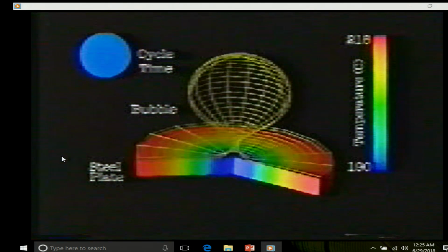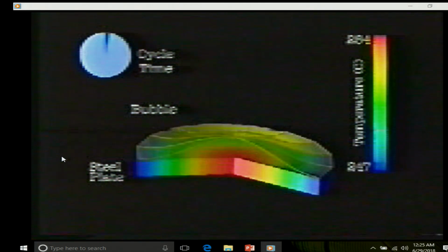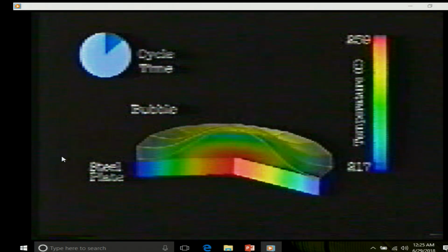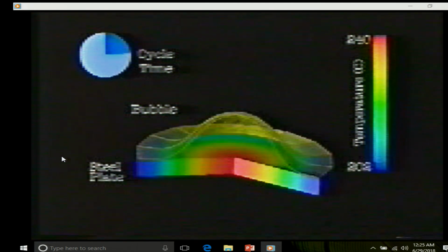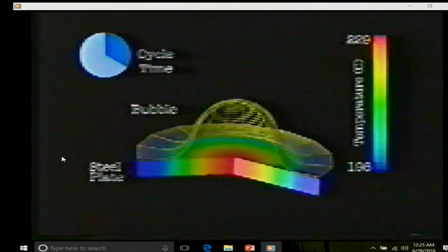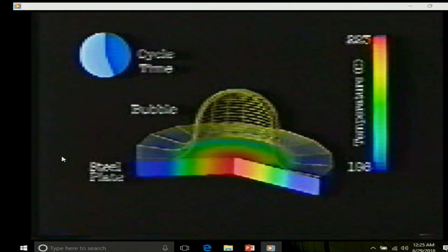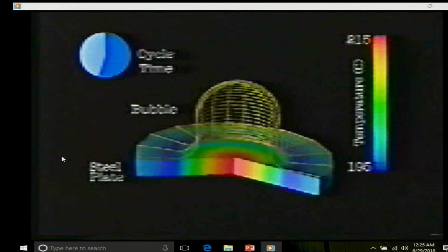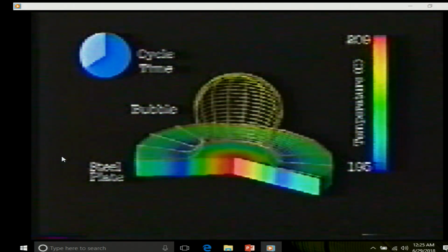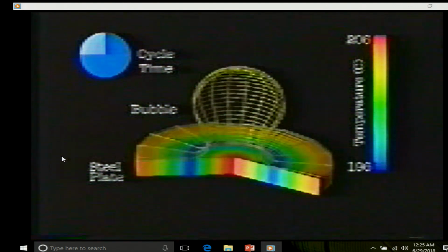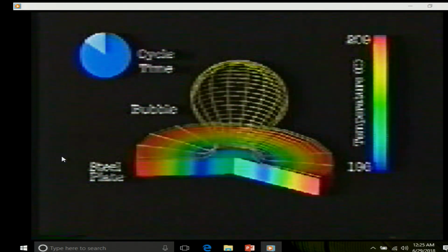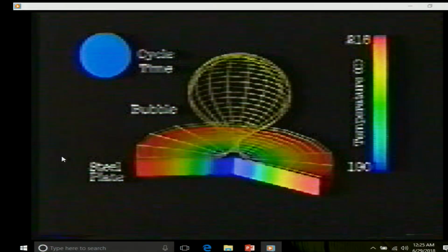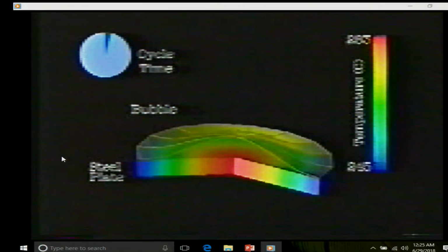But more fundamental than that, my results are showing that the higher the thermal conductivity or diffusivity of the heater, the wider the cold spot, and the higher the total boiling heat flux. So, if I can come up with a material that has even higher thermal conductivity or diffusivity than copper, then I can get even higher heat fluxes.